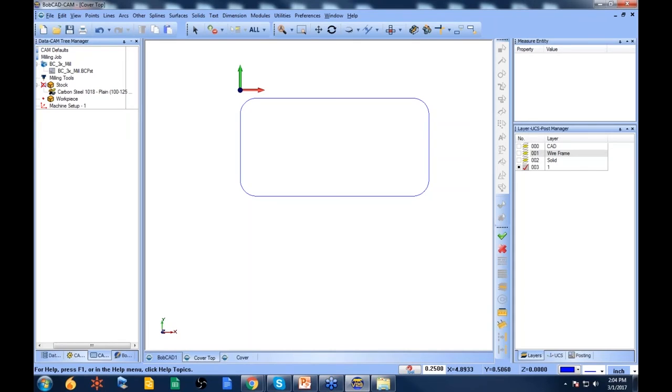Michael, you had a question about importing geometry off of solids, or surfaces and solids. Can you machine it directly without creating wireframe? Yes, you can work on surface edges, and you can also work on surfaces themselves. You can use constant Z, or you can use loop. So hopefully that gets that going for you. Jeff, we'll see you next time.